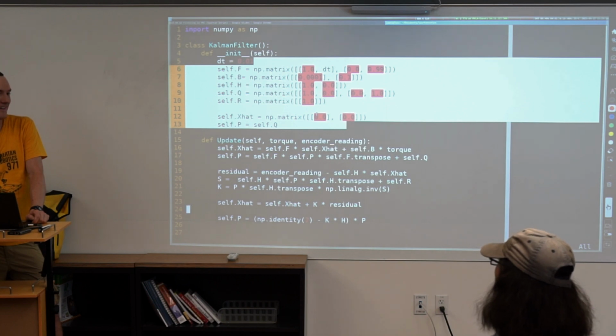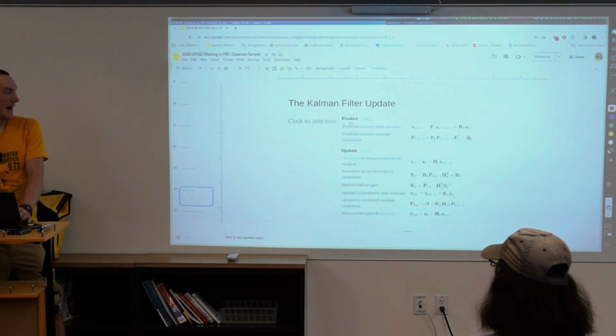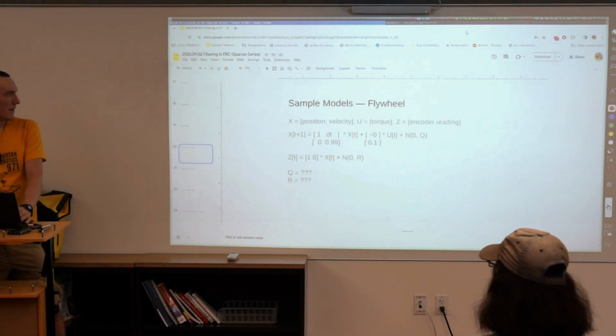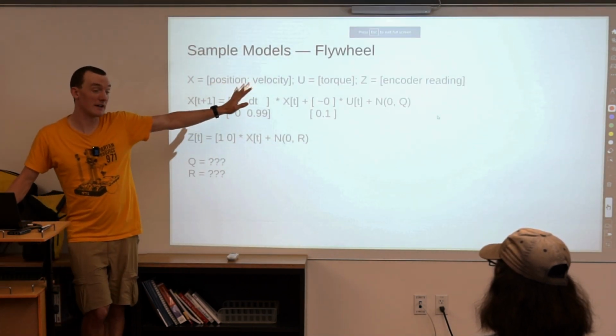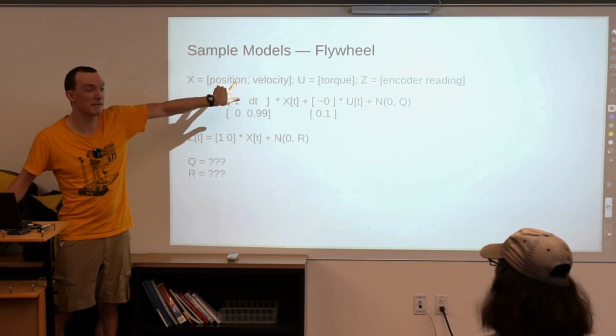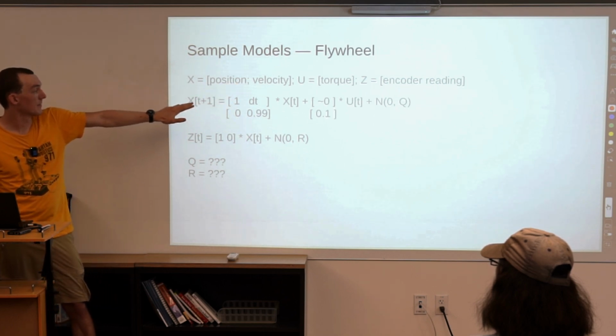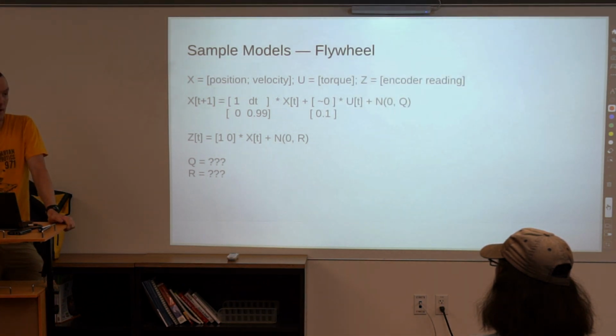How do you do that, defining the right constants? That's where the prior Spartan series talk comes in. Figuring out what states to even use in the first place, like knowing you want to use position and velocity, is not actually always trivial. Sometimes that is very complicated. For most simple mechanisms in FRC, position and velocity end up being what you care about. The rest of these come from the model of the motors and the parameters of your mechanism.